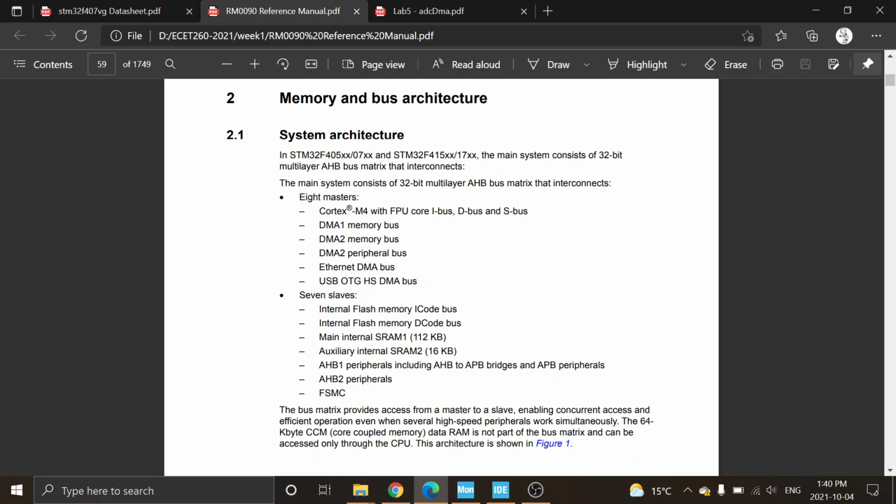There's also another DMA controller that can handle Ethernet. Ethernet has lots of packets, and again, there's Ethernet on board. You just need the physical interface, the actual magnetics to go and put it on the line if you were to plug in a wired unit. Also, USB On-The-Go also has a high-speed bus as well. So all of these different bus masters, any one of them can say, I need to talk to port B, or I need to talk to SPI or something like that.